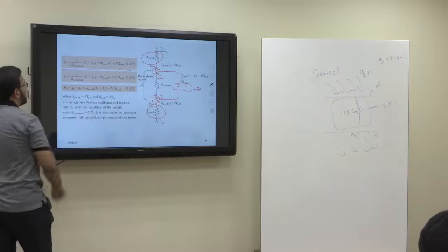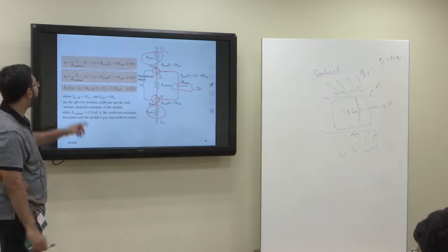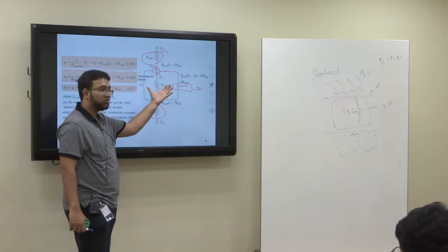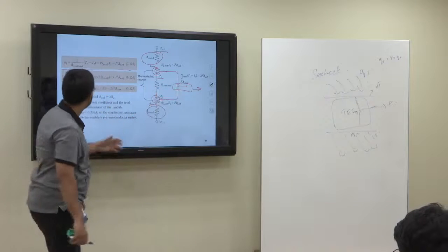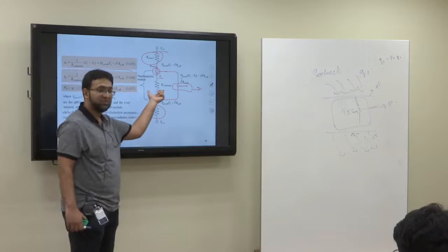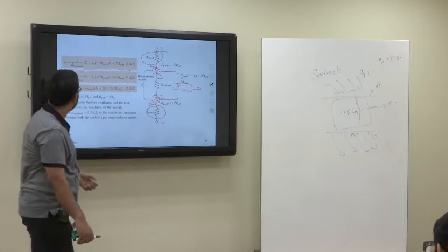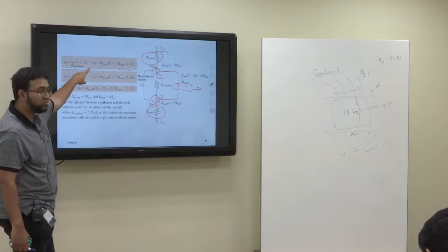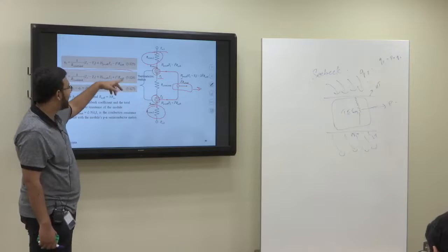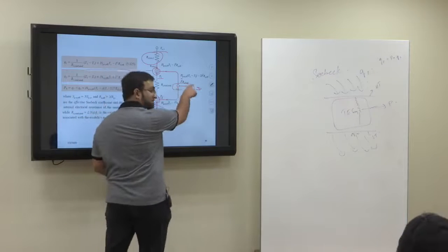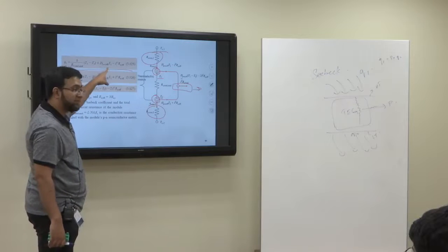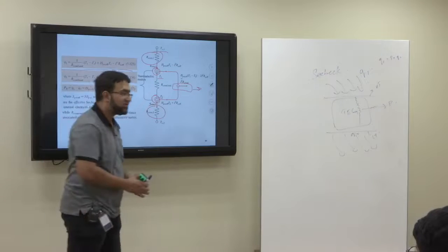So this is 1 upon R conduction of the module. So you have this module. That's the resistance, the conductive resistance of the module, multiplied by T1 minus T2, plus I, the electric current produced, into S_PN effective. S is, as I told you, the Seebeck effect.